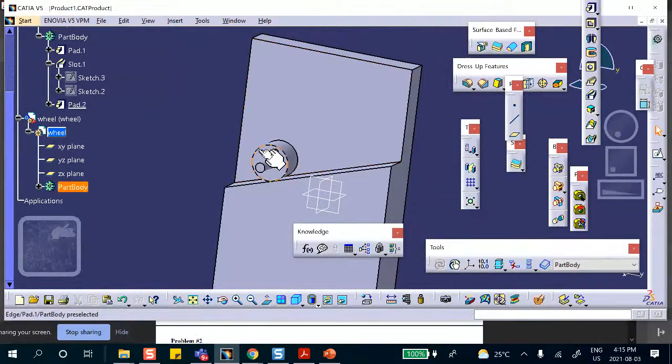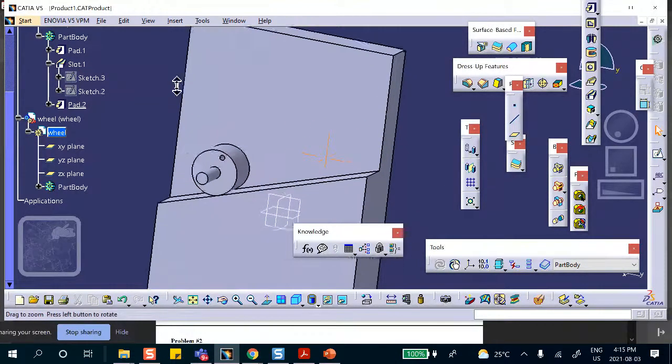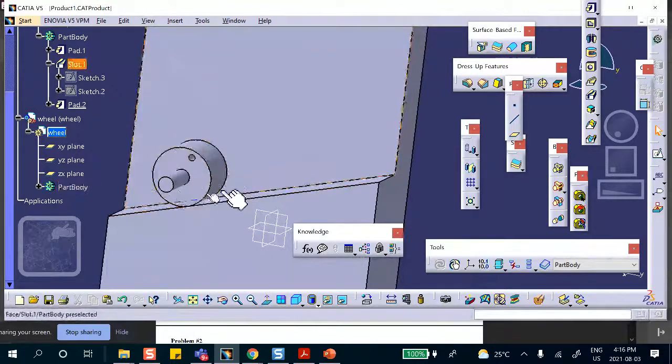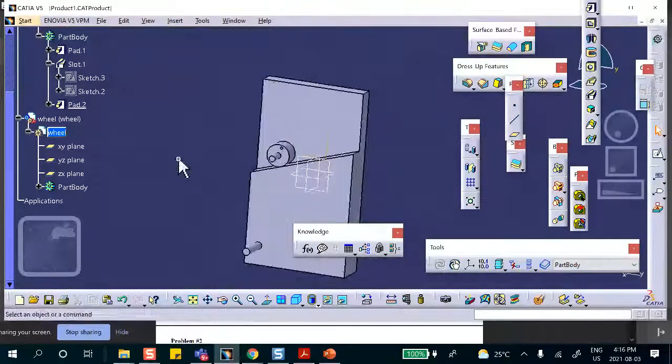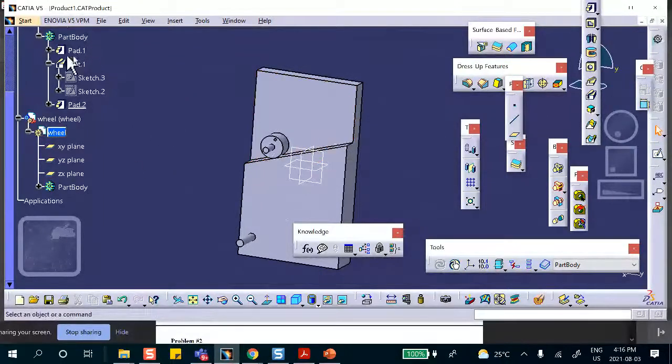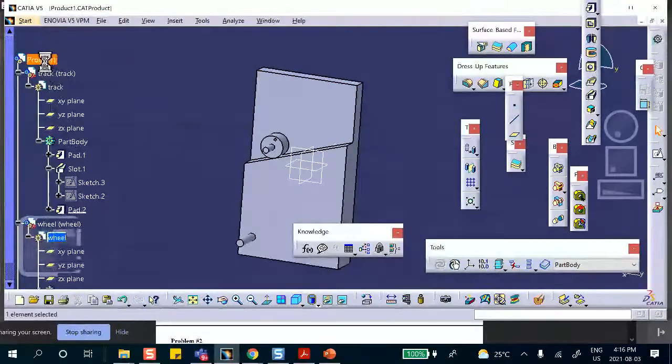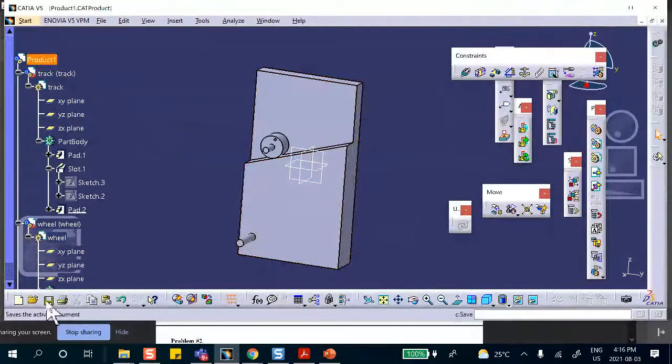By the way, you have to create a point here. For example, you can take the center point of this circle if you want. On the test, when this was given, because I gave people the part, there was a point already there. But for you, you go and create a point anywhere you want. In this case, for example, you can select the center. This is kind of left alone to you to do the rest of the problem if you want. Now, yeah, that's good. So let's go up here and save it.